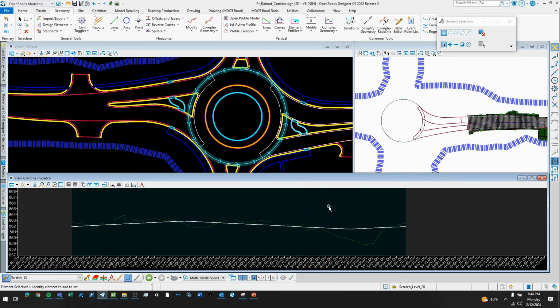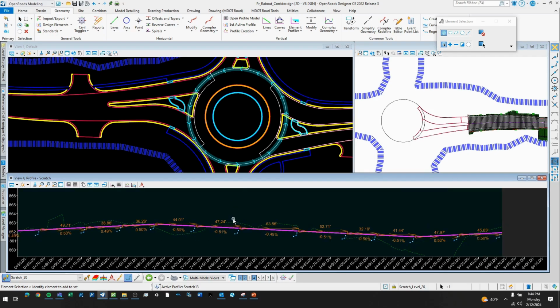And for this, I personally like to try and get a 0.5% in between each line. So I targeted, using AccuDraw, got the station along this, and then started pinpointing, started here at this elevation, matching existing ground, and then either going up or down depending on where I decided my high and low points were going to be. And then mapped it out from there.